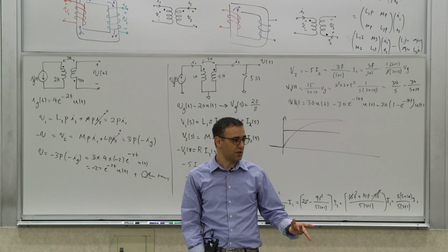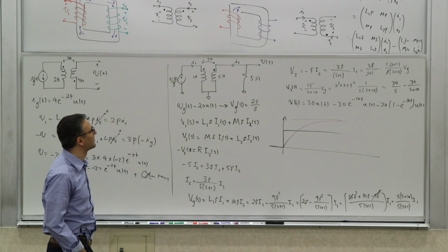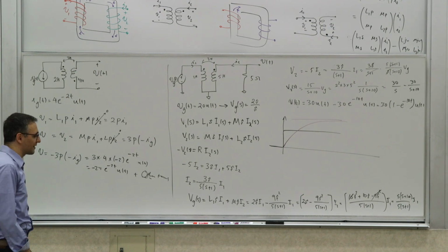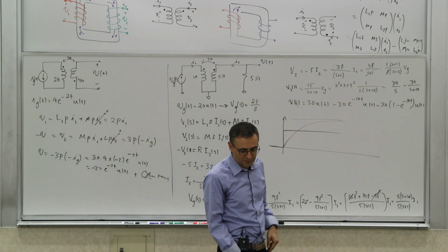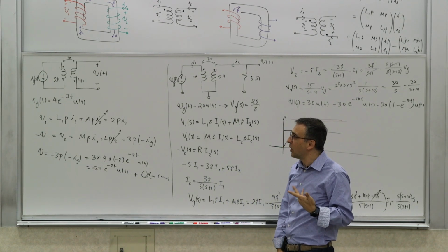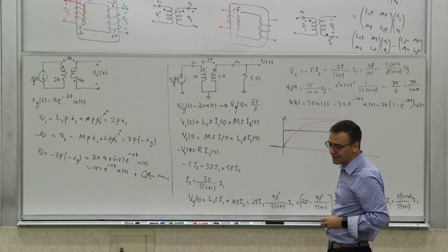There's some energy storage element, right? But what is the order of this circuit? Since these inductors are coupled, the way they are coupled, the order actually is 1. This is a first order circuit because of the way they are connected and coupled. So that's an interesting thing to keep in mind. That's one of the parts of the discussion of the transformer. So these are 2 examples to just give you a sense of what happens.